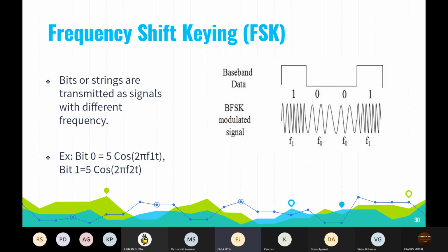So this is a small example of FSK where 1 is transmitted when we have a high frequency of the carrier wave. Since it is frequency shift keying, as per the digital input signal, that is either 0 or 1, we will be changing the frequency of this carrier wave according to the digital input data. So the frequency is reduced when we have 0, and it will be increased when we have 1. We know what is frequency, right?